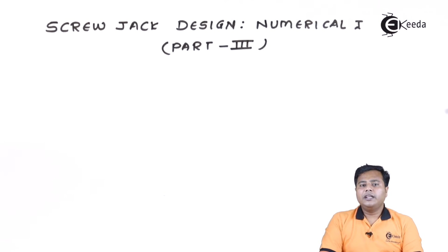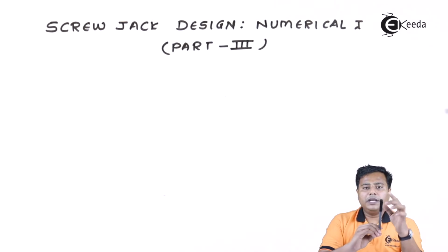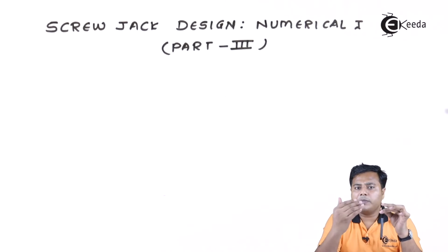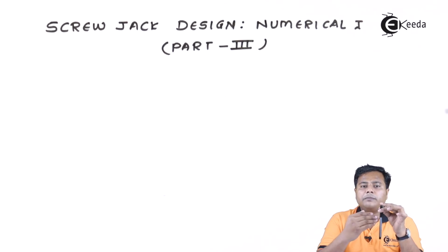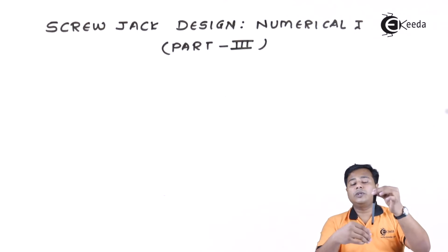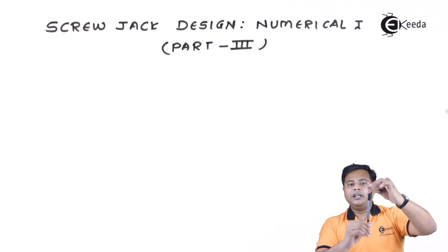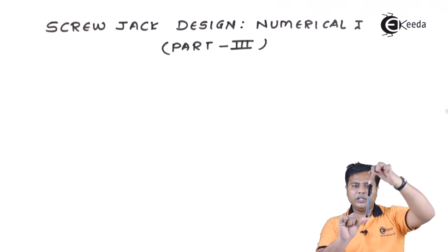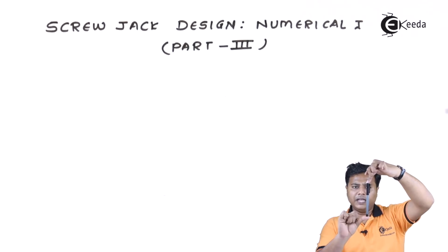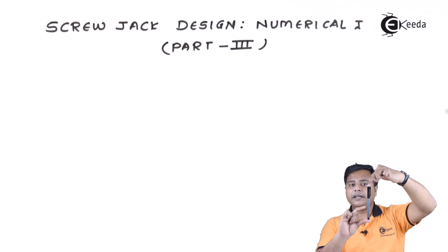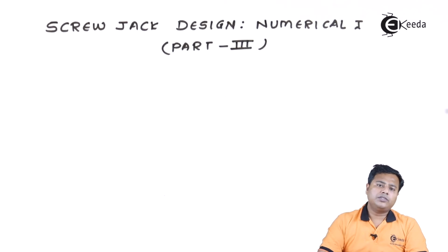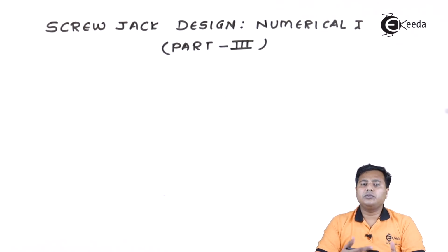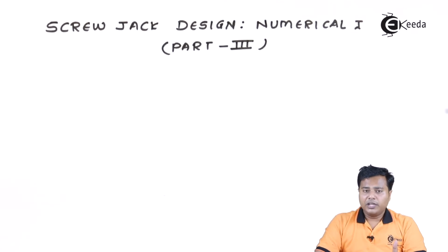Now guys, we know that the screw will be fixed at one end. Failure happens when something gets stuck or the operation fails. Let us say the screw gets stuck somewhere on the upper end and still the operation continues. It will experience compressive loading both from top and from bottom. In that case, it may buckle or cripple or crush depending upon the length. So we have to see whether it is going to cripple or crush, and accordingly whether it is going to be safe or not.